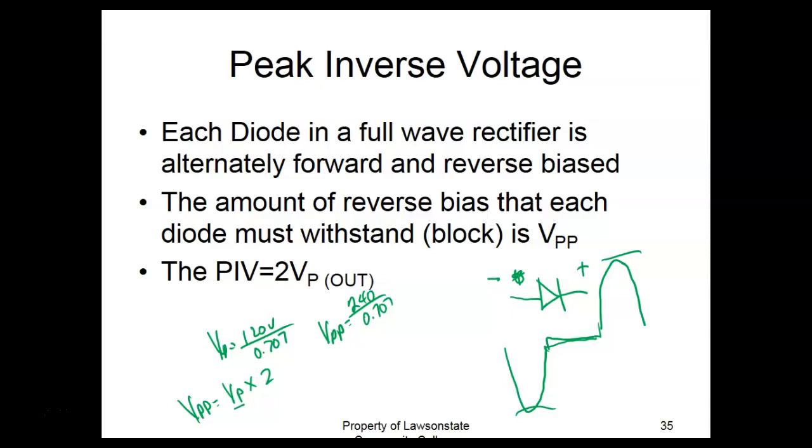So that's the same thing that's going on with your diode. They called it breakover, reverse breakover for a reason. If you break over a diode in the reverse direction and you don't really protect it with a resistor, which these guys are not protected by hardly anything, then odds are it's going to damage the diode. Normally solid state devices can go bad in 3 different ways. They can open, they can short, or they can become very leaky, which means they conduct a pretty good deal of current in the reverse direction, which is not good.